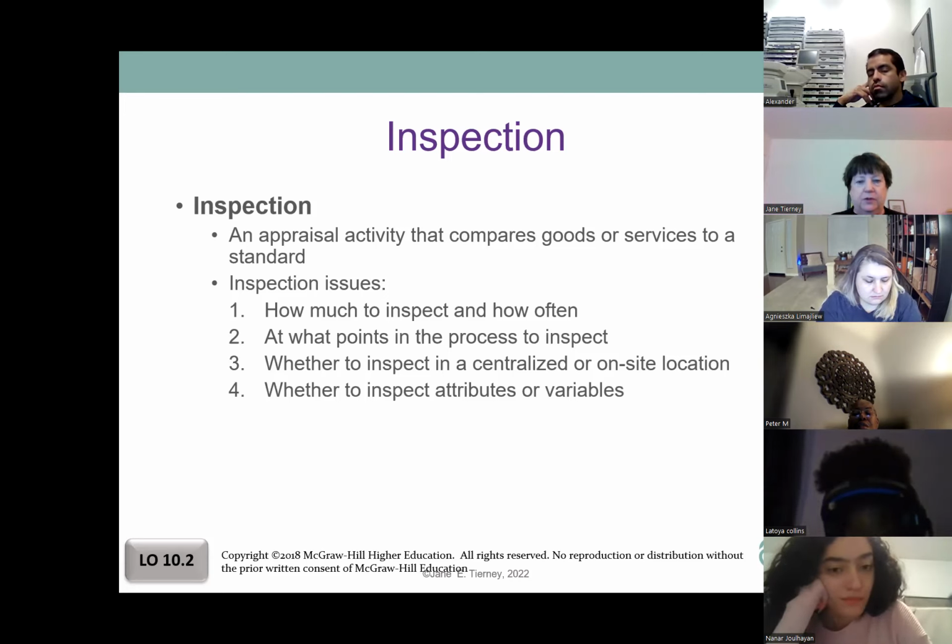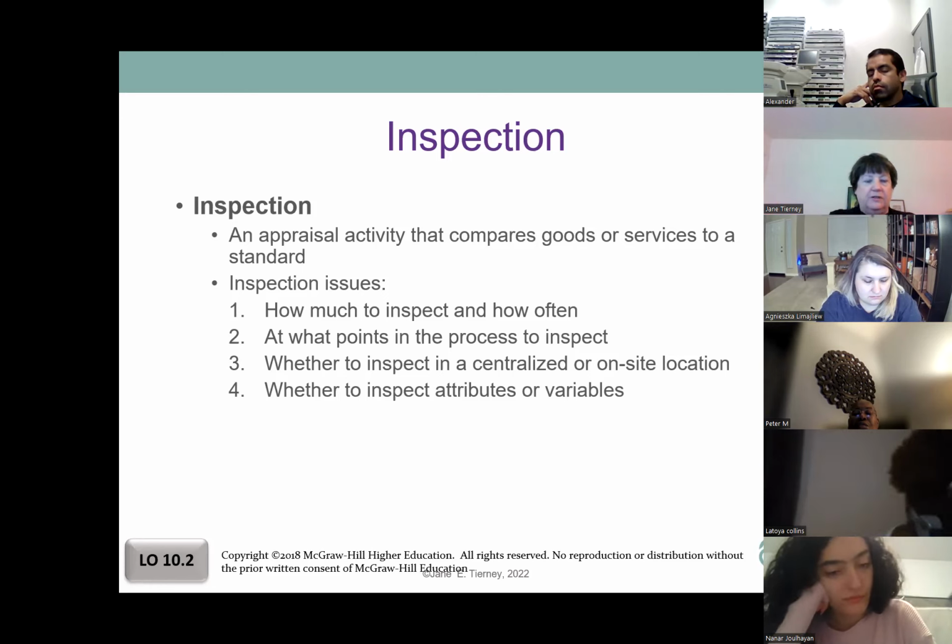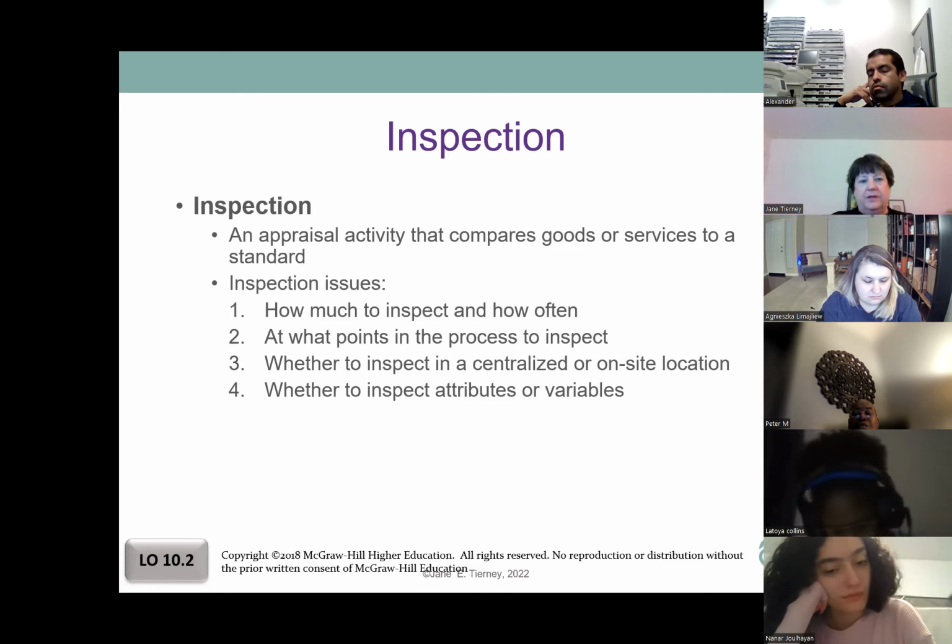So it's the same thing with the roof. You put the roof on with those big triangular pieces, and you get the inspector to come out and look at all that before you start finishing it, because you need them to be able to say it was done correctly. If you start slapping on shingles before the inspector comes out and looks at it, he's not going to know, or she's not going to know, if the roof was installed correctly and if it's going to last, or if it's going to be falling over in the wind or something else.